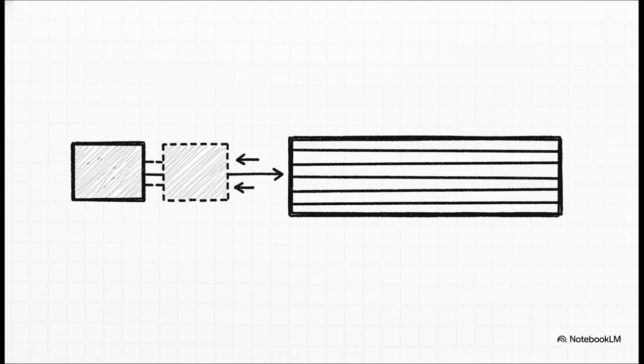So let's think about the actual hardware translation for an instruction like IN AL, 6AH. What is actually happening down on the silicon? Well, data from I/O address 6AH is designated to be input to the AL register. But wait, the address bus is 16 bits wide, so the microprocessor automatically zero extends that 8-bit port address. The 6AH becomes the 16-bit address 006AH. Finally, this full 16-bit address is physically pushed across pins A0 through A15 on the address bus. And that, right there, is exactly how the hardware routes your 8-bit software command.